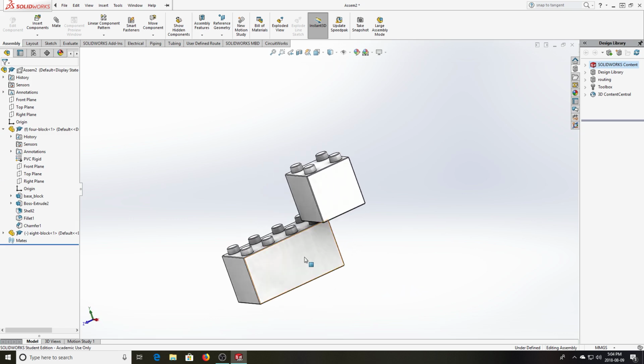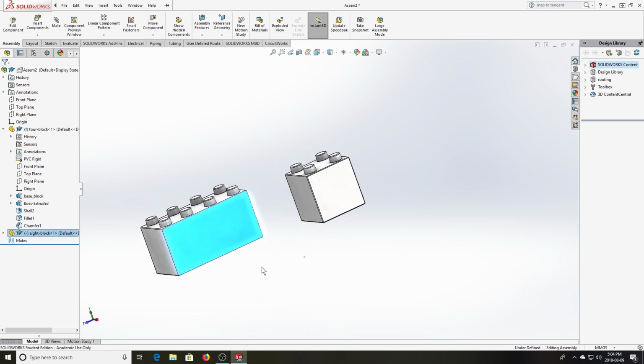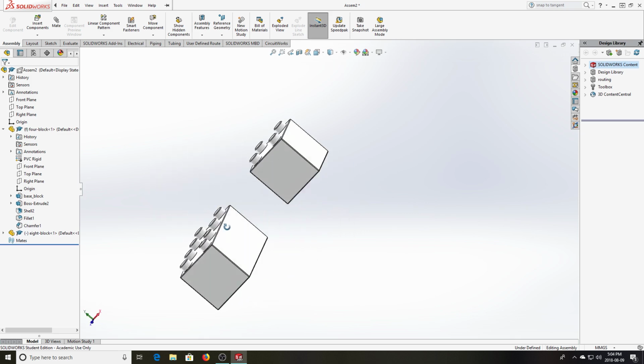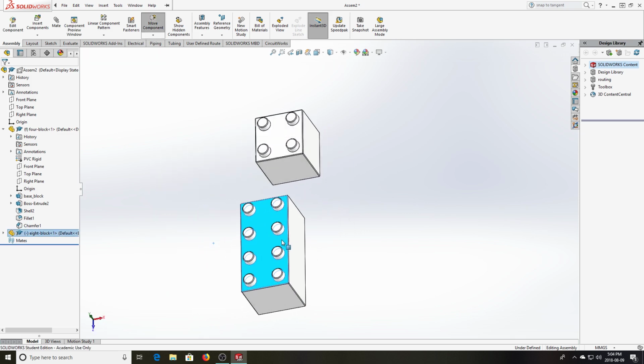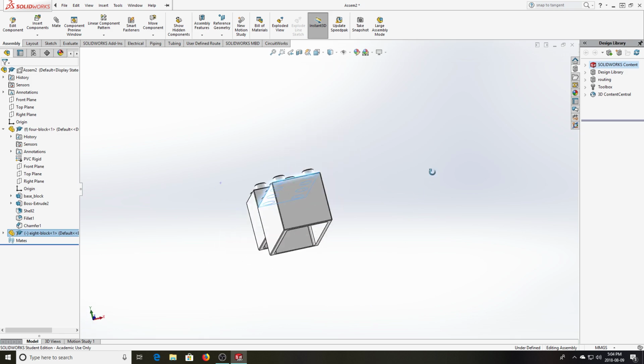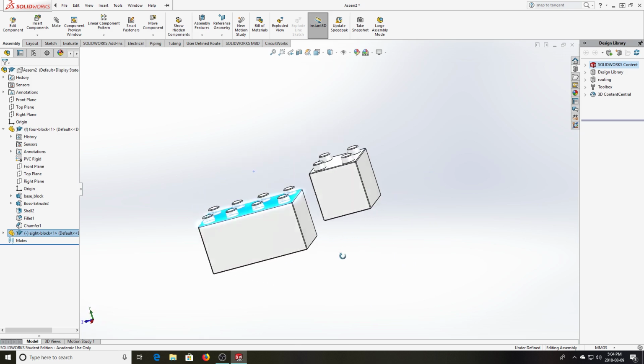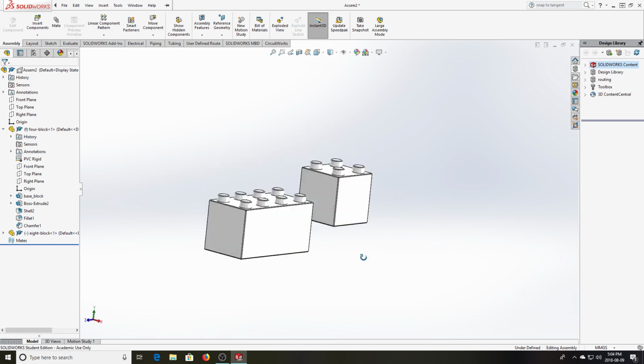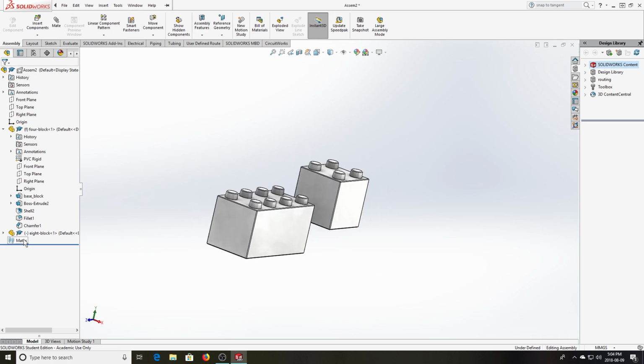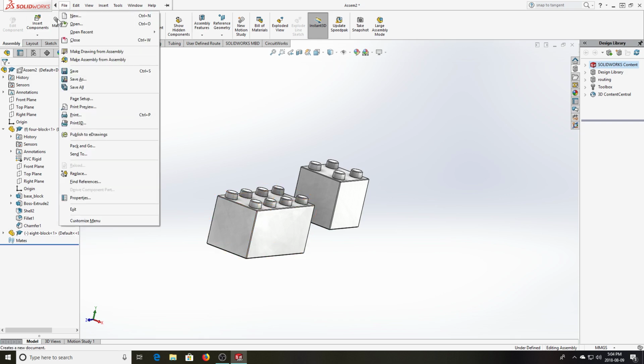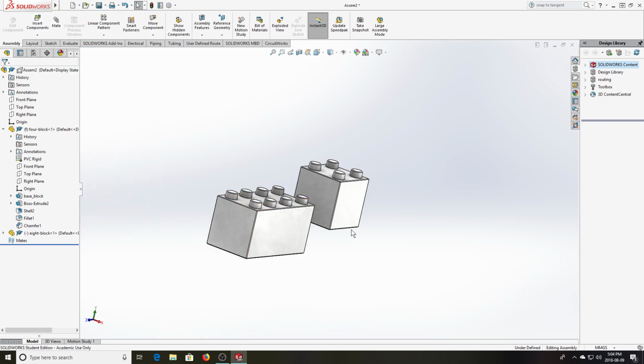Now, it just is kind of random the way it got placed. I didn't want it to be there. So how do I move it over here? Because it's in this infinite ocean of space that is not well constrained. Well, there are these things called mates. These are the relationships between parts that you need to come to terms with. And so what I'm going to do here is specify how these parts are to be mated.